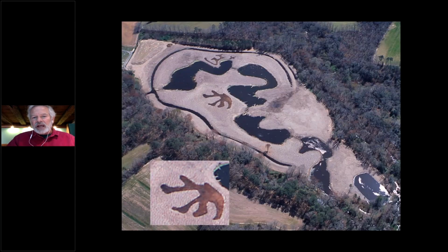The next slide's maybe a little easier to see, but this is where we have the riffle grade control in the stream, and it backs the water up into this very long recharge bed, or seepage reservoir. The only way for that water to get out is to flow laterally through that carbon-rich sand, where the water is being stripped of its excess nitrogen and phosphorus, and sediments are being trapped as well.